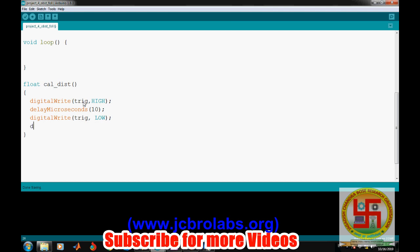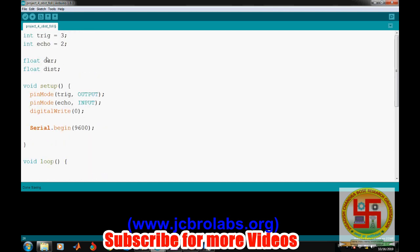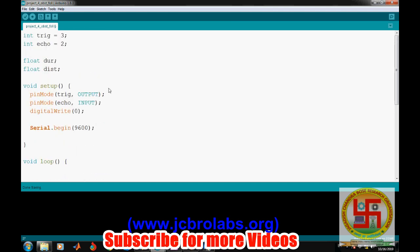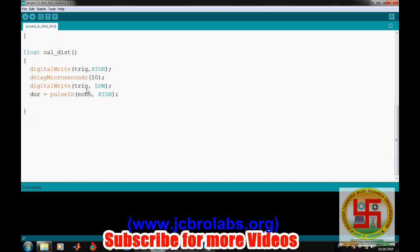Okay, so for that we will calculate, because we have created this duration variable. So dur equals pulse in. There is a built-in function, and then add the echo pin, and then which state, high state. Okay, and then we should calculate this distance variable, right.